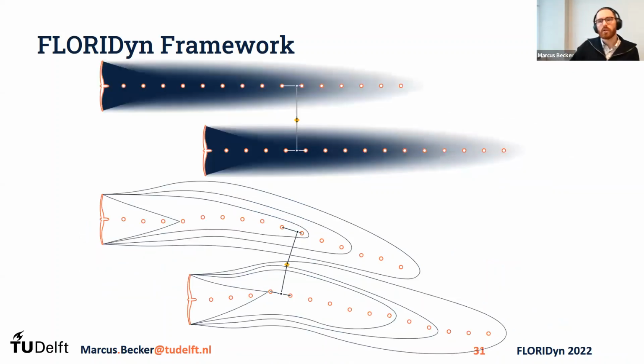And now the interesting part is that we can also do this with multiple turbines. So if we have the lower part, we have the world coordinate system, we have a yellow marker, and we have two turbines in heterogeneous flow. And then we do the extrapolation from the center lines of both turbines. Then we can create an effective wind farm, we're calling this temporary wind farm, at the location of the yellow marker. So this wind farm is only relevant for this one point and doesn't necessarily have to agree with the current layout of the wind farm, but it agrees with what the marker is experiencing at that time instant.